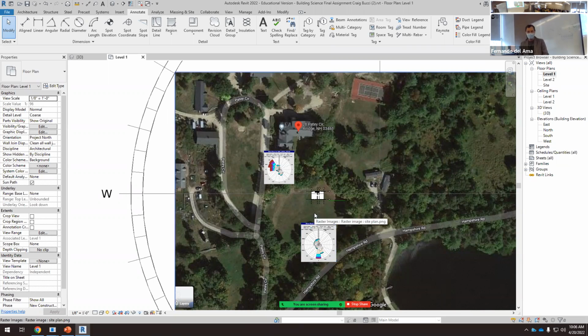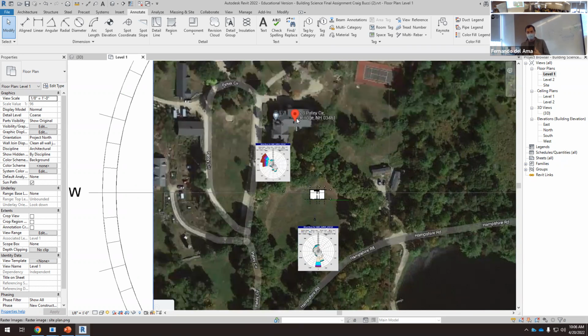Okay, you don't have to calculate it, but we need to know that if we place solar collectors for domestic hot water in all these buildings, in summer, it's not that we can't use this amount of hot water, it's that it can damage the system, because we can overheat the system because we're not using this hot water. So that's why we need to release this heat to the pond.